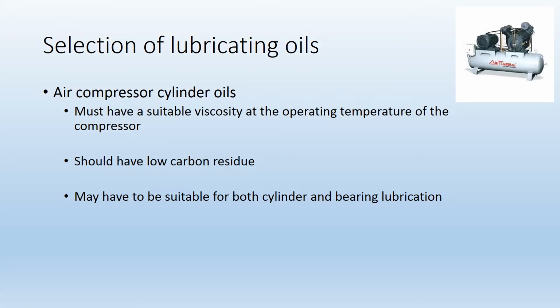When selecting air compressor cylinder oils, consideration has to be taken so that it has a suitable viscosity at operating temperature of the compressor. The oil should have low carbon residue to prevent deposits of carbon on valves and cylinder walls. Also, the lubricant should be compatible for the cylinder walls and the bearings of the machine.